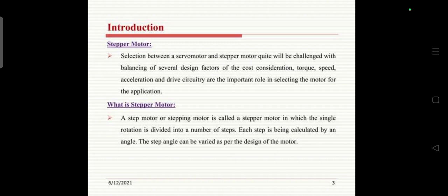And what is a stepper motor? A step motor or stepping motor runs step by step only, in which a single rotation is divided into a number of steps. Each step is measured by an angle. The step angle can be varied as per the design of the motor.